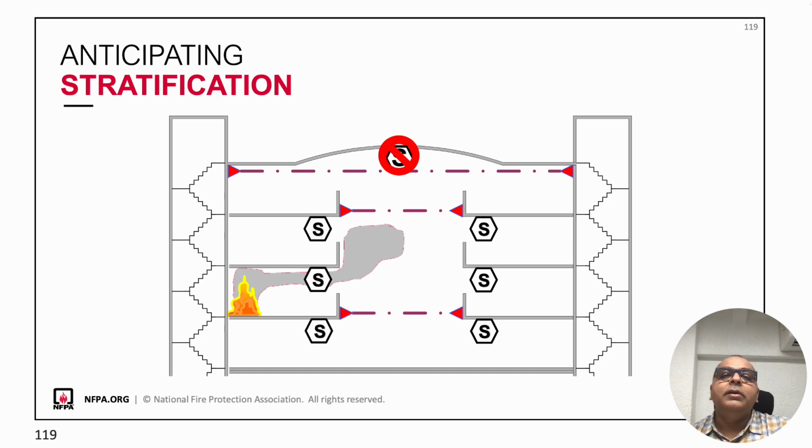To ensure early detection, use multiple levels of smoke detectors. Avoid relying solely on ceiling detectors installed structures. Consider aspirating systems for layered environments and understand the expected smoke spread at different fire sizes.